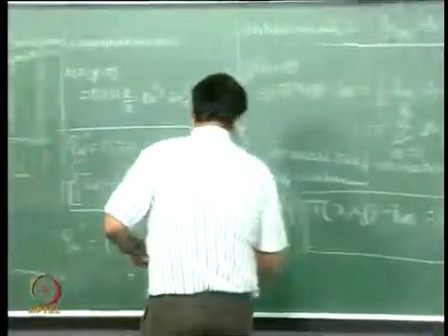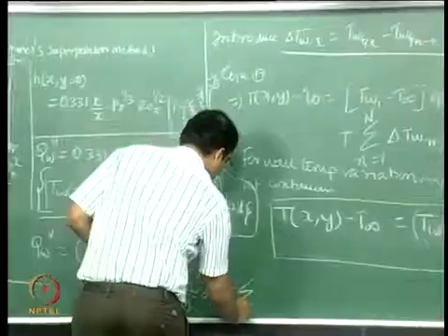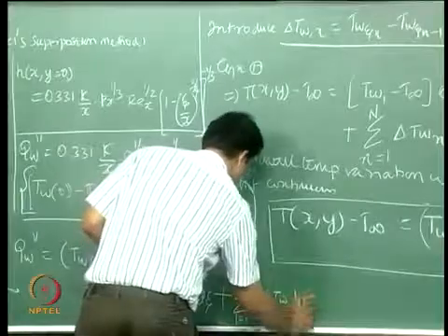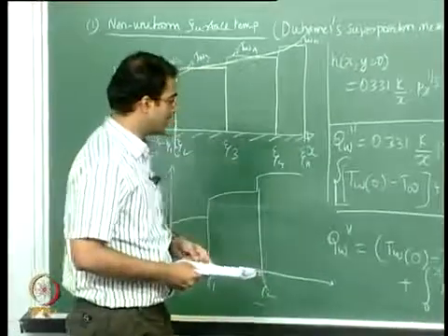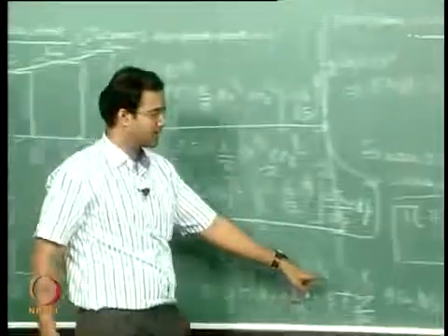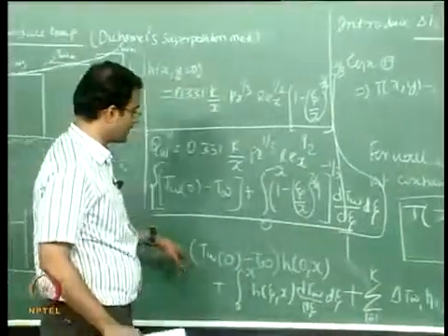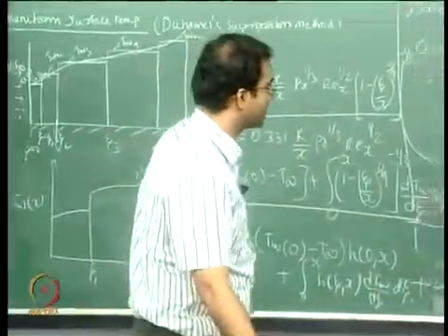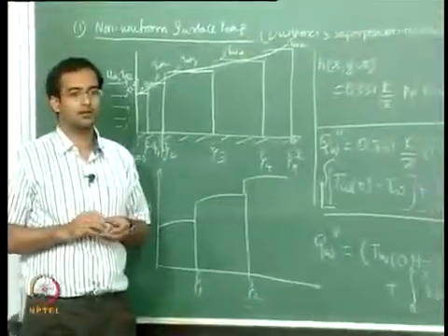Okay. So summation, suppose you have say k number of jumps. Okay, I am going to go from i equal to 1 to k delta t wall into h, that is it. Okay. So this will take care of both the continuous variation wherever, and wherever you have discrete jumps at these locations you have to write as delta t h and sum them. Okay. So this will give you the local variation of heat flux. So with this we will stop. Tomorrow we will solve an example for assuming a linear variation in the wall temperature, and we will see how to calculate your wall flux. Okay.